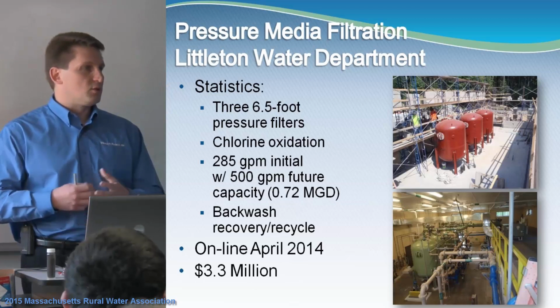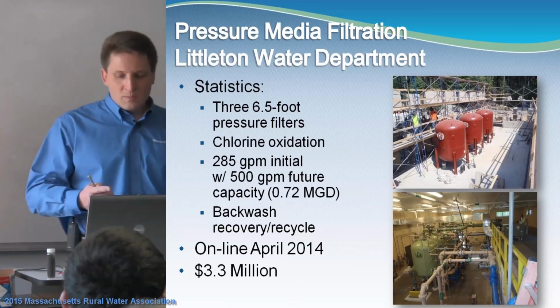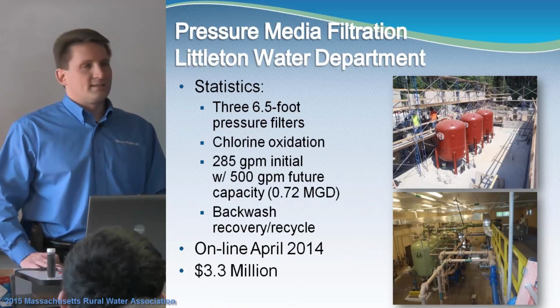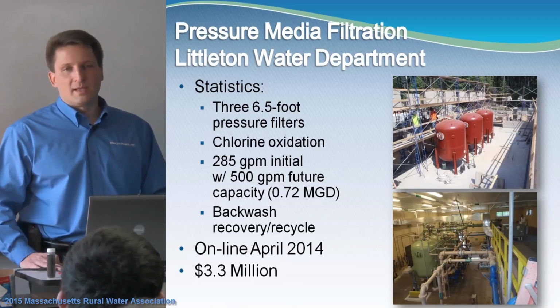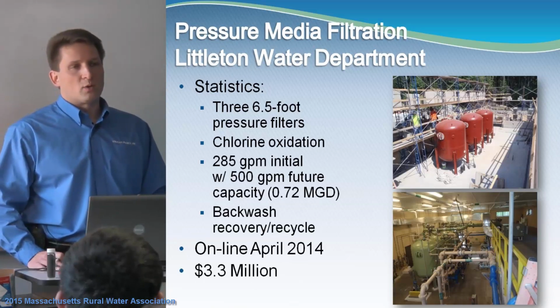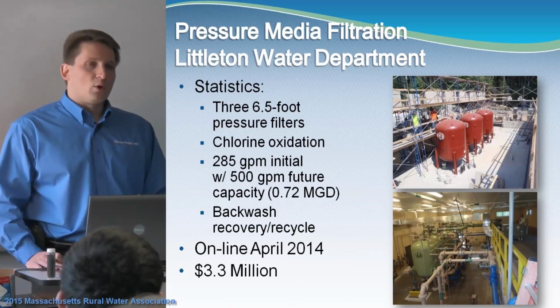So in the future, all they'll need to do is just put more water through the facility and not do any other upgrades. Chlorine was the only oxidant used as part of the process. One of the things that a lot of people think about is, hey, I have green sand, I have to use permanganate. That's not true. You don't have to use permanganate. Sometimes your water quality will dictate that use. But for Littleton's sake, they only needed chlorine.